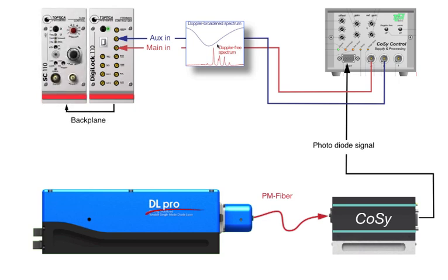The Digilock is connected to a scan control unit via an internal backplane connection in a DC 110 supply rack. The scan control will act only as a voltage amplifier to supply the PCT inside the laser head. The internal scan generator has been disabled by setting the trigger switch to external. For this first locking tutorial, no other connections between the Digilock and the laser head are needed.